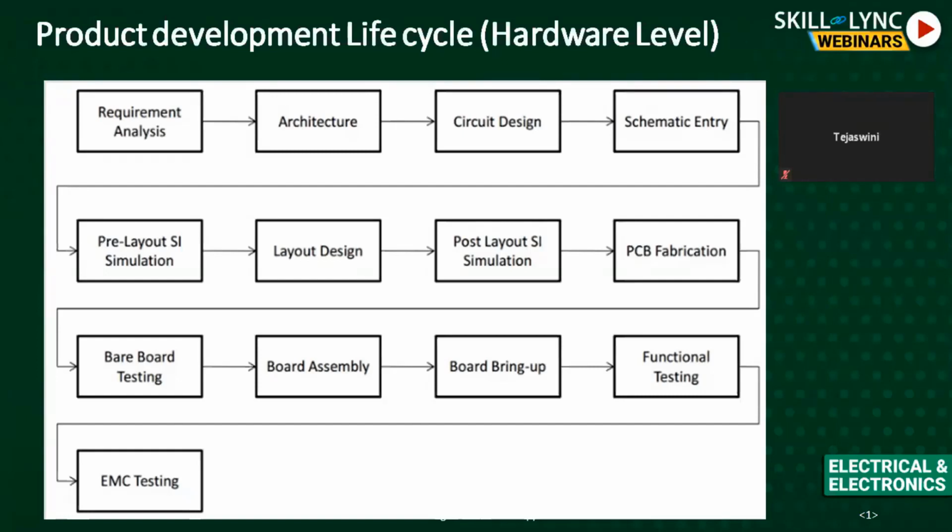Signal integrity is used everywhere nowadays because the tools support it. And it is really good to check whether most of the signals we are using are properly there or not, and whether they adhere to the standards or not. And then the layout design. After the pre-layout SI simulations, we go for the layout design. Here we do the complete layout of the schematic, and afterwards we do the post-layout signal integrity simulation.